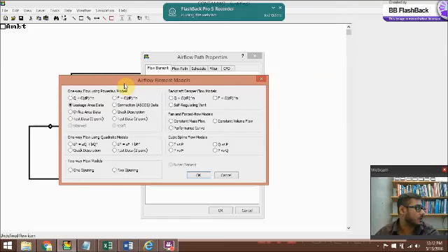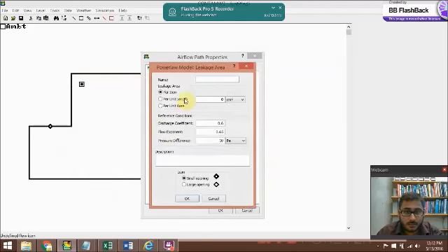One would determine only the leakage area, and the second would be for the door. You can give an opening schedule to the door. Okay. And the actual location on that wall doesn't matter unless you are doing a CFD model, because it'll just assume uniform concentrations in the zone. Yes.